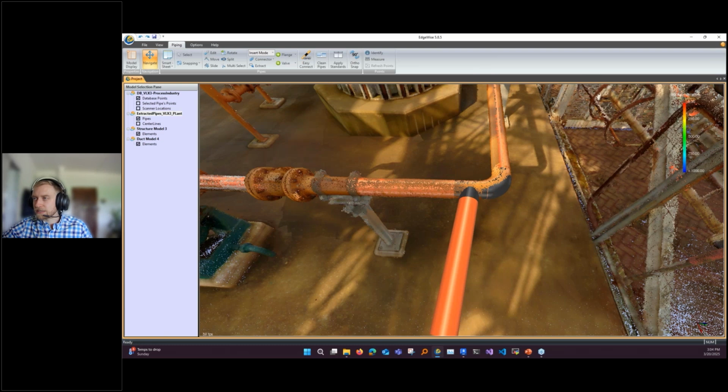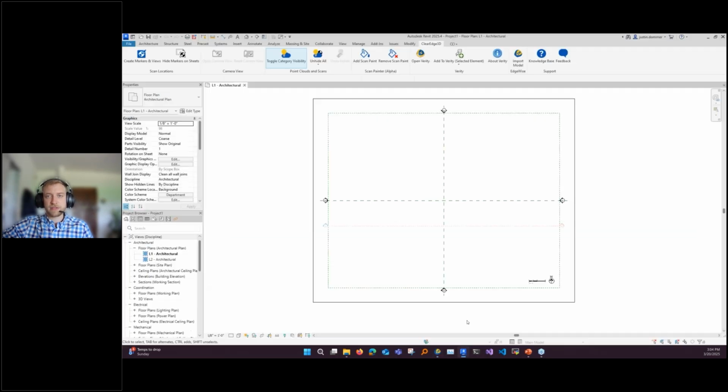Revit contents. Interesting. So anything with the Revit plugin, I would really recommend anyone who's using Revit on a daily basis really check out the ClearEdge3D tools for Revit. It's a free plugin. Mainly, it's got some very nice functions for actually controlling the point cloud, but it also has the new version of the import tool, which is way more flexible.